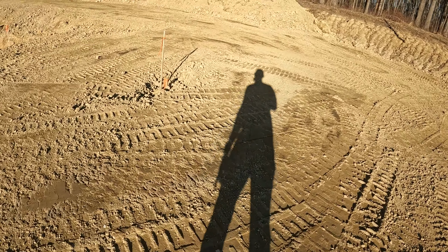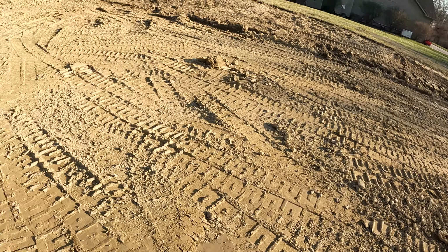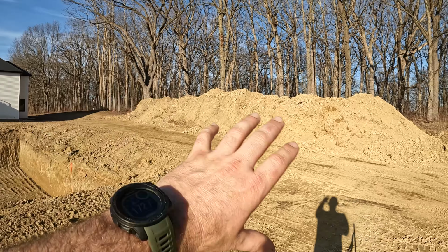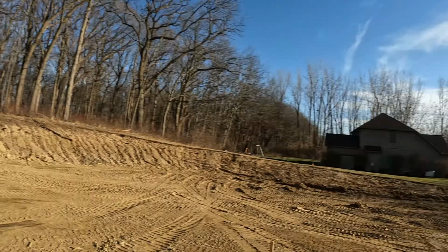Don't mind these other stakes. I'm kind of going backwards here, but these are for the next foundation that we're going to have going in over here. And you'll see we have a big pile of dirt back here still, and we didn't cut everything out. It's because we need to have enough dirt left on site to backfill and grade away from the foundation. So we don't want to pay to bring dirt in when we've already got all this dirt sitting here on site ready to go. No need in spending the extra money.